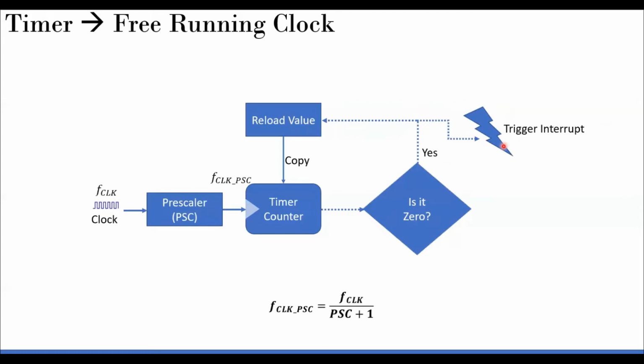Of course, you will not be using a dedicated timer for that. You will be using the SysTick timer option for that, but the concept remains the same. So you give a reload value and check whether the counter is counting to 0. The moment it becomes 0, you trigger an interrupt, and you write an interrupt service routine corresponding to this interrupt vector, like the discussion that we had in the previous lecture. You write something there and it will execute that.